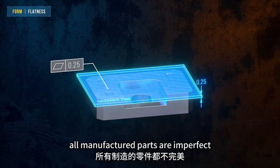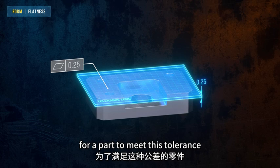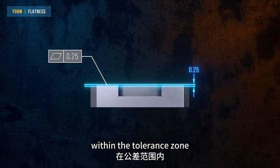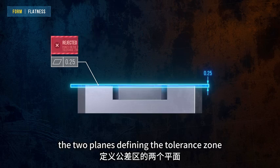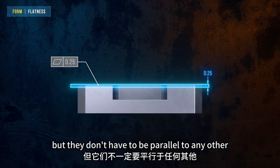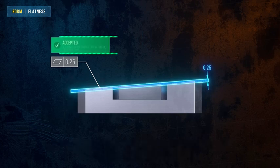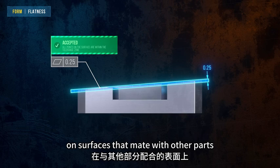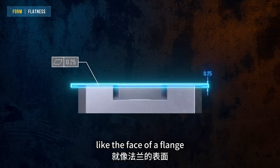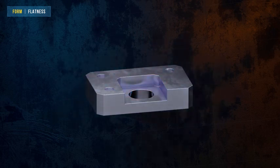All manufactured parts are imperfect. For a part to meet this tolerance, all points on the surface must be located within the tolerance zone. The two planes defining the tolerance zone are parallel to each other, but they don't have to be parallel to any other surfaces. Flatness tolerances are often specified on surfaces that mate with other parts, and need to have even contact, like the face of a flange. Flatness